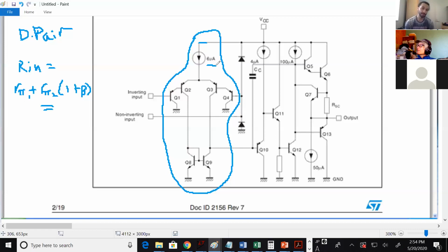Because you know that the Darlington pair will give you a lot of current. So, because it's like beta times more. Yeah, it will. So any current, this thing can provide current. This can supply a lot of current, but if this was connected here, it would be even more. But it has something to do with this RN still. So that's the hint. Why do you think you use less current in the diff pair than you do over here in the gain stage?